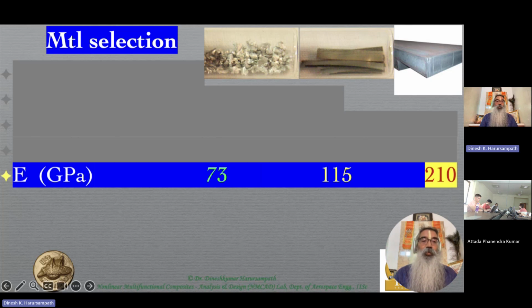Even before that, we need to take note of the units we are using here for E, which is gigapascals rather than megapascals, which is 1,000 megapascals. So it's a much, much larger quantity compared to sigma U. And that's kind of clear because, as you might recollect, the Young's modulus is nothing but the proportionality constant in the linear limit between the tensile stress and the tensile strain.